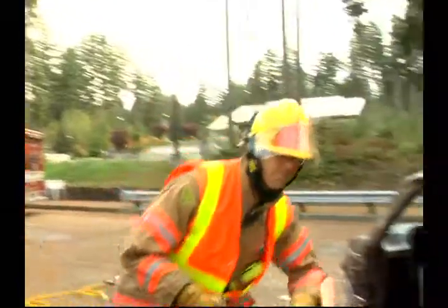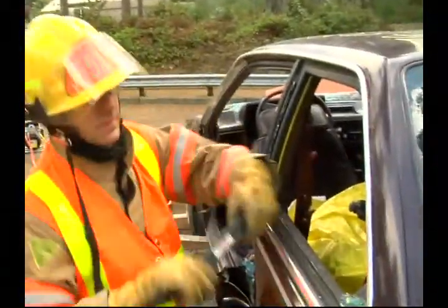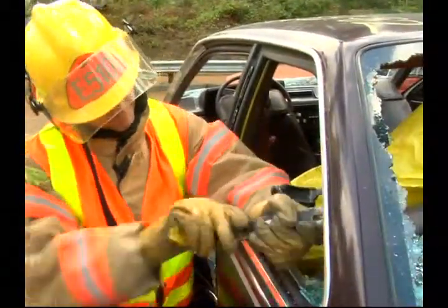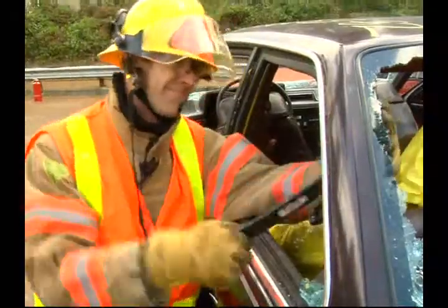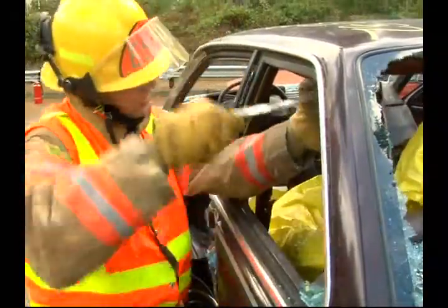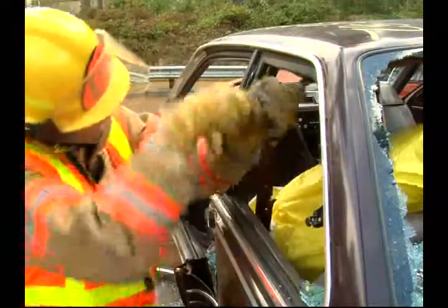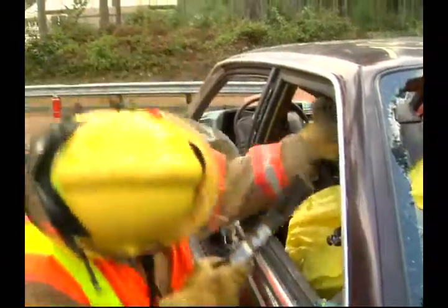Before you do any cutting on the roof, it is imperative that you locate and recognize the presence of loaded roof-mounted airbags and their pressurized gas cylinders. To do this, peel away the trim along the roof rail and inspect the revealed area.